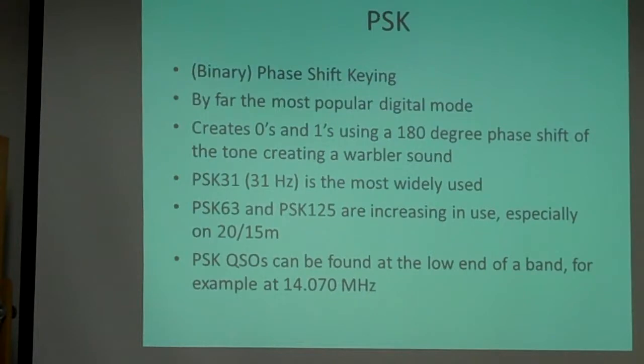2,500 hertz, which is in sideband, you'd use all of it, right? In PSK 31, you can have 15 or 20 QSOs in that same single channel space that single sideband would operate in. Okay, each independent of each other. 63 uses twice as much roughly, and 125 4 times as much as that 31 hertz shift.